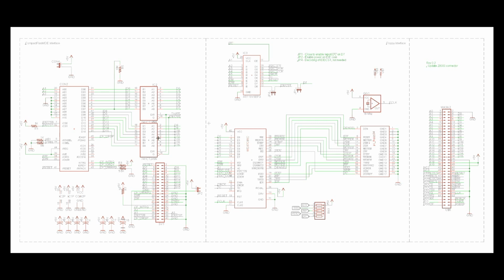There's another buffer here for the upper 8 bits. This is a 16-bit computer. Right now, the BIOS does not use the upper 8 bits. We run in the 8-bit mode. So you could probably leave this one out, save a few pennies. Just plain ordinary 74HCT245s. There's some resistors for pull-ups and stuff. You'll see the standard stuff here on RC2014s and stuff like that.